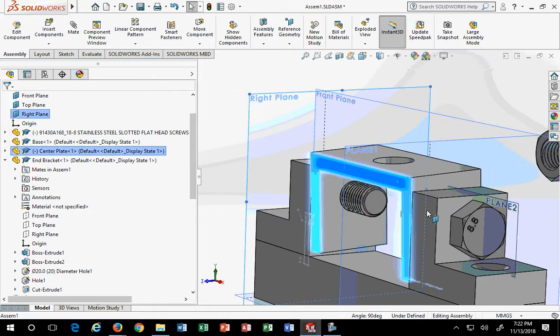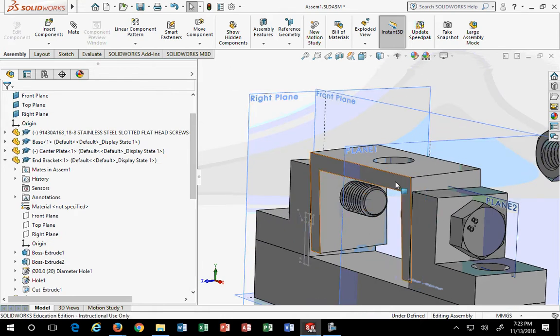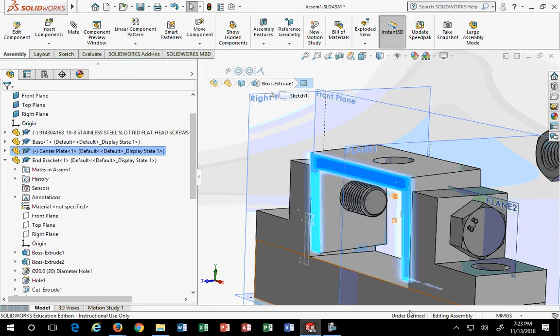Let's find out. But what I'm doing right now, the quick way to get to mate, if you hold your control key down, remember how the quick way to get to constraints was? Remember that when I told you just hold the control key down, pick the item, and you see it on the left side? Well, guess what?